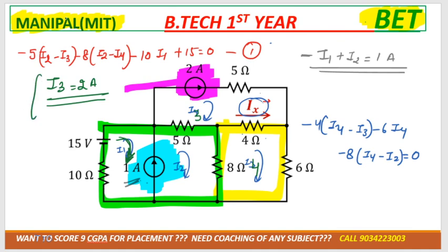So the i3 direction and the 2 ampere direction are the same, so we can directly write down that i3 is equal to 2 ampere. Okay, so as you can see, we'll have 4 variables and we'll make 4 equations. 4 equations you can't do through a calculator also. You just need to substitute. You can substitute the i3 value over here, and then you can solve it.